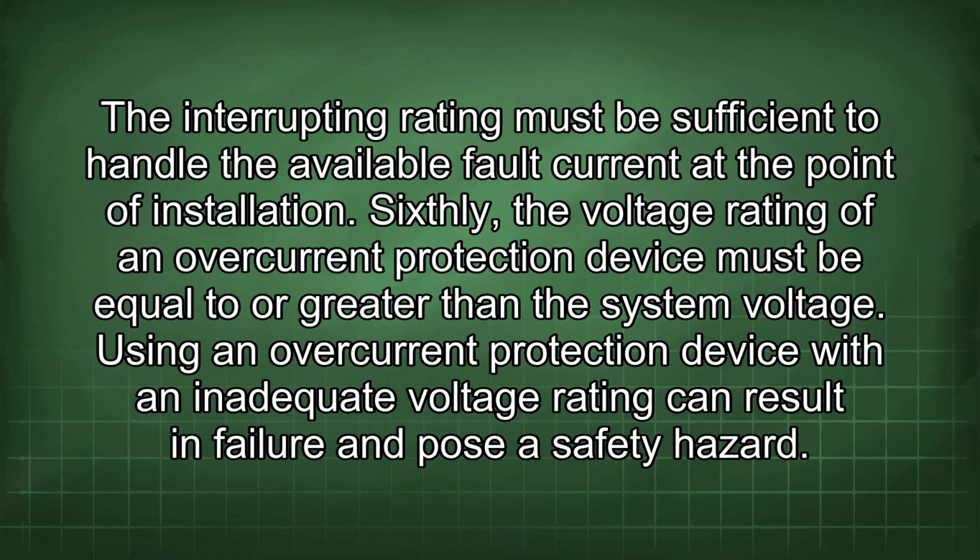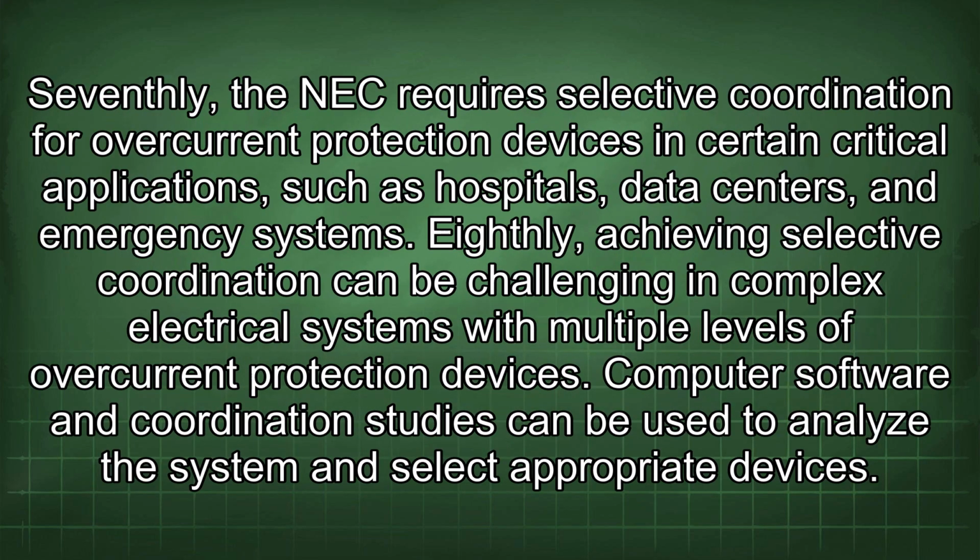Using an overcurrent protection device with an inadequate voltage rating can result in failure and pose a safety hazard. Seventhly, the NEC requires selective coordination for overcurrent protection devices in certain critical applications such as hospitals, data centers, and emergency systems. Eighthly, achieving selective coordination can be challenging in complex electrical systems with multiple levels of overcurrent protection devices. Computer software and coordination studies can be used to analyze the system and select appropriate devices.